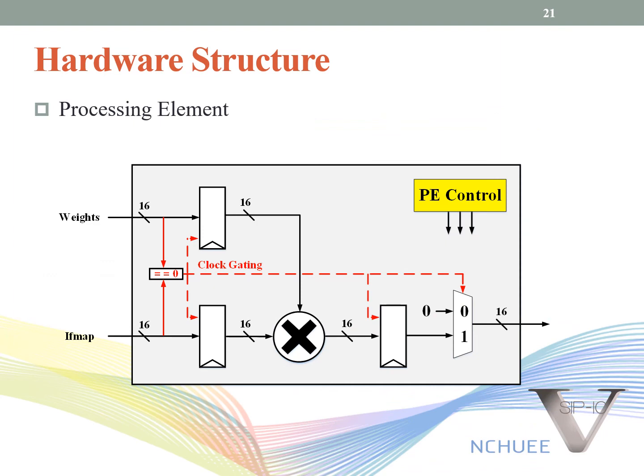Since the characteristic of ReLU will cause the feature map after the first layer of a deep learning network to have many zeros, we have configured clock gating inside the PE so that the multiplier and D flip-flop can directly output 0 without any action, to reduce power.